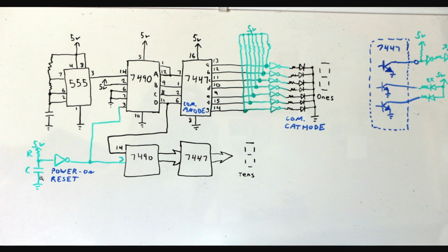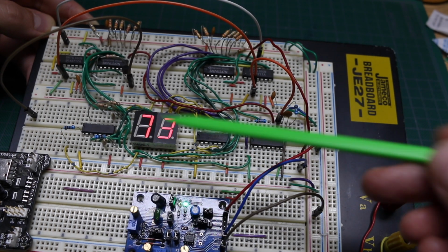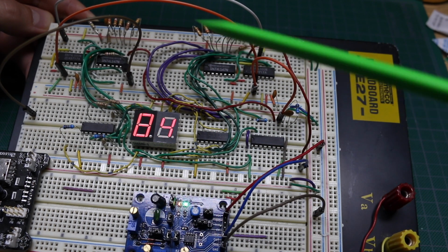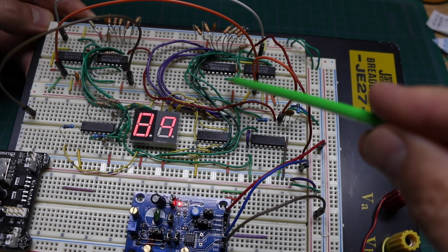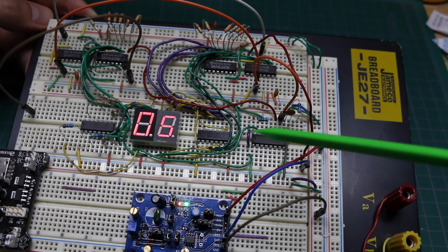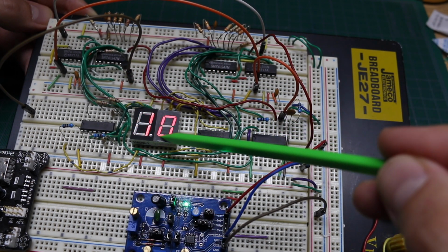Eventually the capacitor charges enough to cross the input threshold from 0 to 1, so the output goes from 1 to 0. And now we are in free counting mode, so we power up with 0, and then everything starts counting properly. The circuit got a little messy, especially as I kept changing it and adding to it, but here's the 7447 and 7490 for each digit, and the inverters to drive the correct display here.